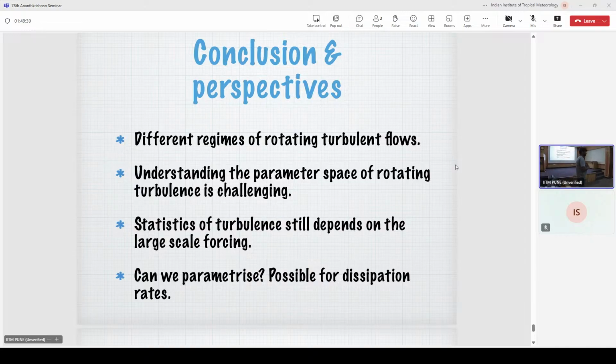So again, the ratio depends on the Rossby number, like how nonlinear the turbulence is versus what the rotation rate is. And there is a spatial distribution of the rods, whether they prefer the outer radius region or near the center. That depends on the wall friction. So usually they prefer to be organized near the central region. If you have a rotating turbulent tank, you have Ekman layers on the bottom and on the edges also. So you'll have preferential concentration in the inner turbulent region.